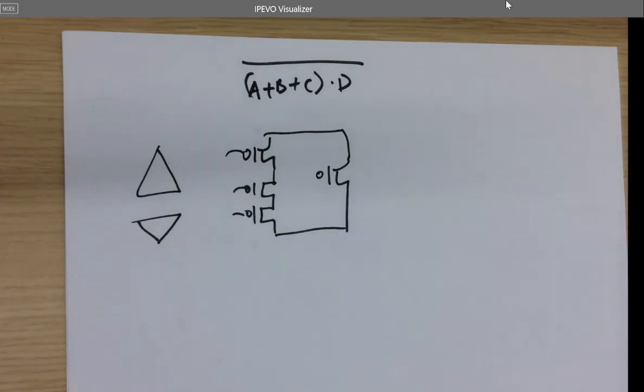Because the 3 transistors are in one line, I have to redesign the circuit carefully in order to make them in parallel. There are some ways that you can remember it. If you have 3, doesn't matter if it's NMOS or PMOS, right? Like this. How do we make them in parallel? It's basically just this, right? Always. So 3 parallel transistors in stick diagrams, it's always being drawn like that.